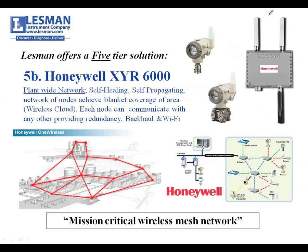This gray box at the top, which you've seen a couple other times in my PowerPoint here, actually acts like a cell tower. It's called a multi-node. It has 3 radios built in. The black radio on the bottom communicates out to the battery-powered, industrial, very accurate and capable field devices. The antenna on the right will throw Wi-Fi, so you can literally create a Wi-Fi hotspot within your plant. This antenna here communicates to other wireless multi-nodes. So it's kind of like putting cell towers up in your environment.